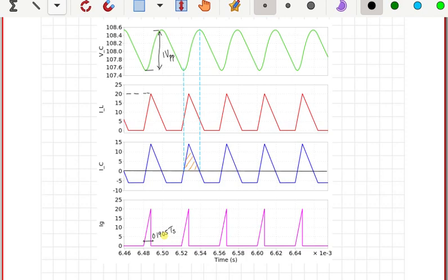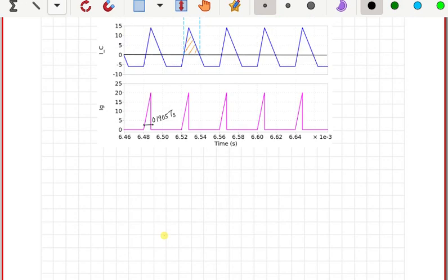And then that results in a very large value of peak current in the device or through the source, whereas the average value of this component, so you can calculate what is the average value of Ig by assuming a 100% efficient converter. Ig is going to be V0 I0 by Vg, right? So this will give you 108 into 6 divided by 340. So this is something like 1.9 amperes you will get for the average current,